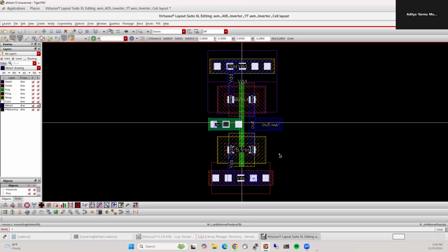But in the next video, I'll go through DRC, LVS, and parasitic extraction or PEX. So we'll do those three things. We'll incorporate that for this inverter and then check the performance of the inverter, characterize it and see how parasitics have affected the inverter, right? So that process of DRC, LVS, PEX is very important. And we're just using a simple example of an inverter right now to go through it.